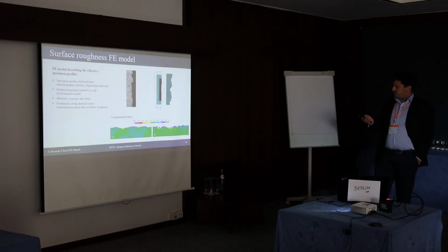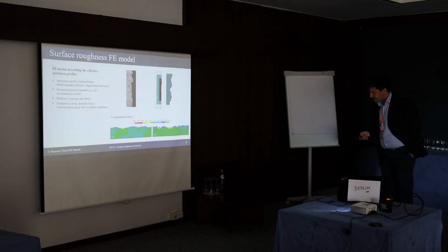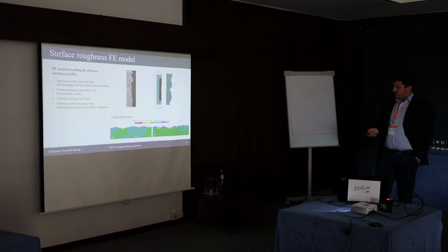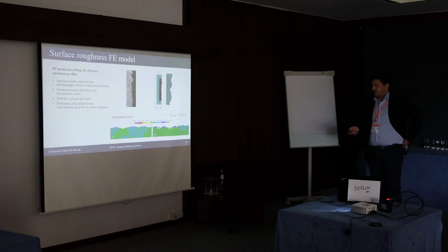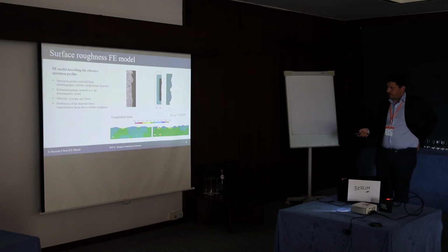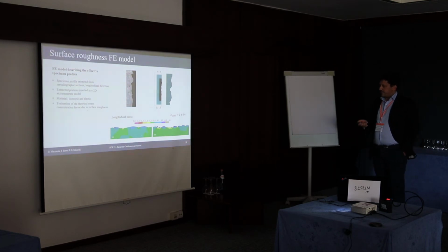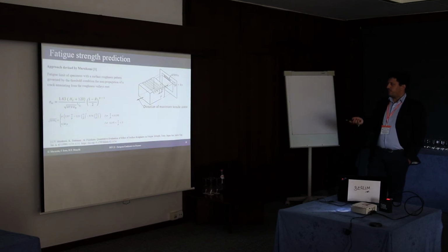What we obtained is that here we can see the longitudinal stress of the baseline condition and of the ATU condition. For both materials, the theoretical stress concentration is not one. Also in the baseline case, we have a theoretical stress concentration. But if we compare the two conditions, the stress concentration is almost double. But when we see the fatigue results, the effect is not so large.